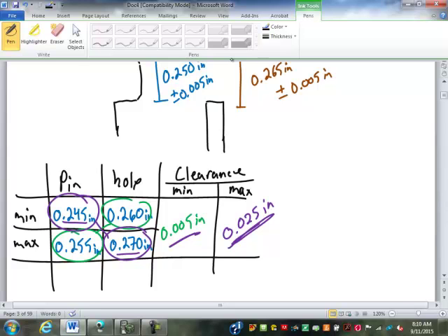Well, it happens every now and then, even with pretty good quality. You can see here, just a 5/1000ths tolerance, or 5/1000ths allowance, I should say, gives you a range of 20 thousandths difference. So if you have a bolt at its minimum dimension and the nut at its maximum dimension, you can have a pretty good gap between them, a clearance.